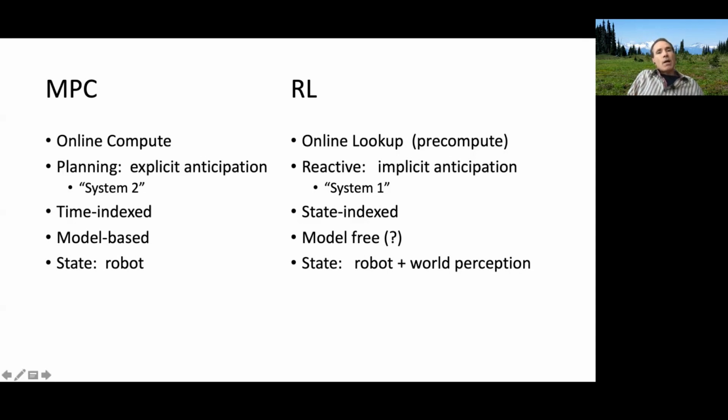And yeah, okay, it's also useful to remember that the online solutions we compute with MPC are time indexed versus state indexed on the reinforcement learning side. The time index can actually be very useful for many movements. If you think of this notion of muscle memory or chunking of motions, one can imagine that having some kind of time indexed memorization of what's needed for a particularly fast sequence of motions is a really useful framework, as opposed to needing to get feedback at every point in time.